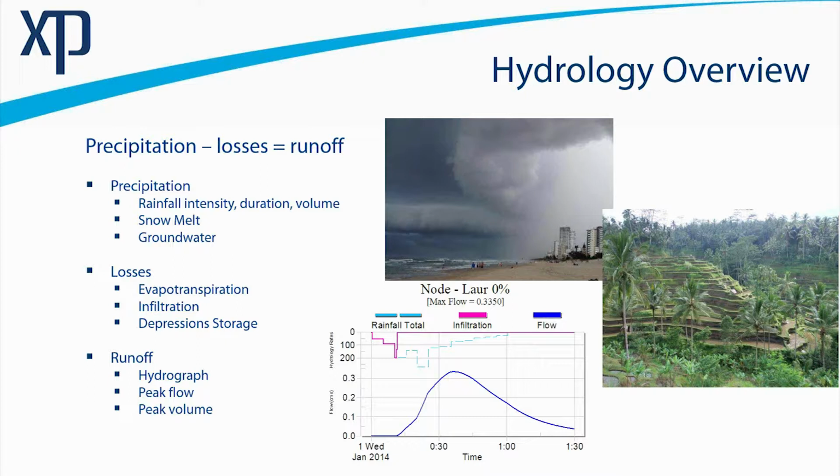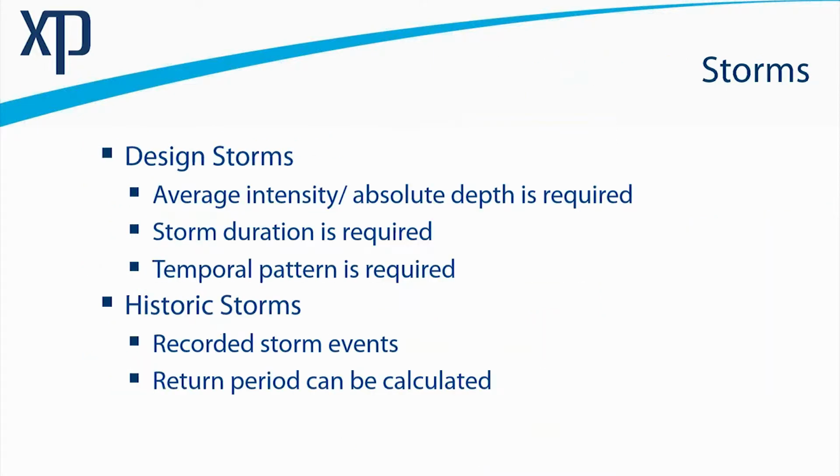And of course, the result of that assessment is to derive a hydrograph, which can inform us about peak discharge rates, but also, very importantly, the volume of a particular storm event, whether it be a design storm event or a historical event that's being back-modelled. So, design storms and historic storms. Design storms are a tool that is supplied to the engineering fraternity to allow us to predict based on a retrospective view of actual rainfall events for design purposes.